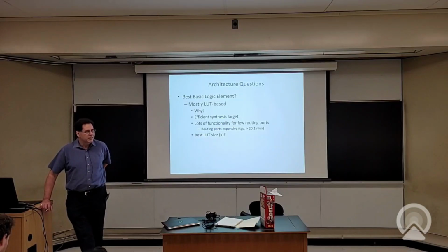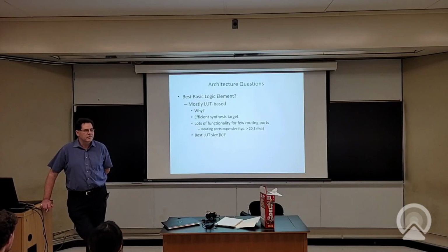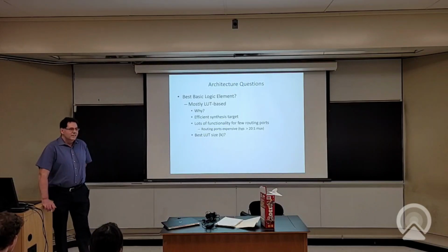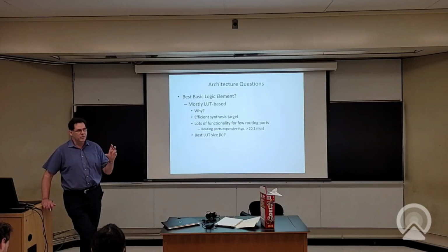I guess, yeah, it seems to me that for a while there have been 4-LUT designs out there, and 6-LUT designs. It seems there's probably room for reuse across process nodes and just sticking with 6-LUTs. Yeah, they change other things. They're changing how their logic blocks work, how their routing is constructed, and how their arithmetic works. But you're right, the LUT structures themselves went 4-LUT for a long time, then fracturable 6-LUT, and then it tweaks exactly how that works, but nobody's gone to a 7-LUT.